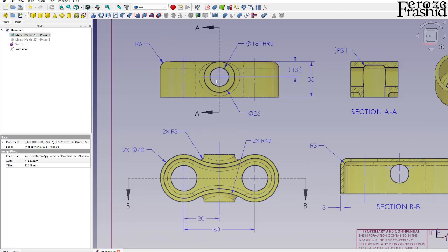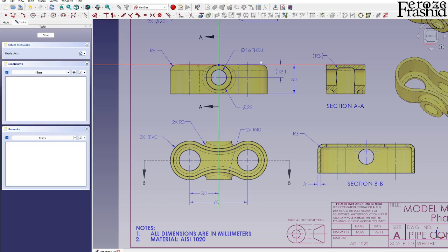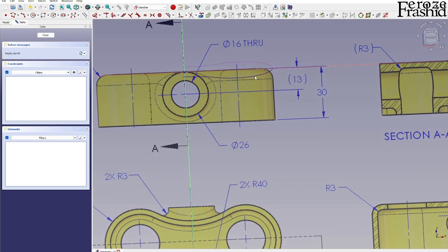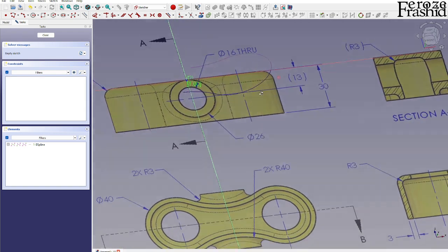All right, so now I want to draw this sketch on XZ plane. Okay, here, and I want to take this line as my reference, and that is GX from the keyboard. So that's external geometry, this command GX, and that should give us a dot to work with.